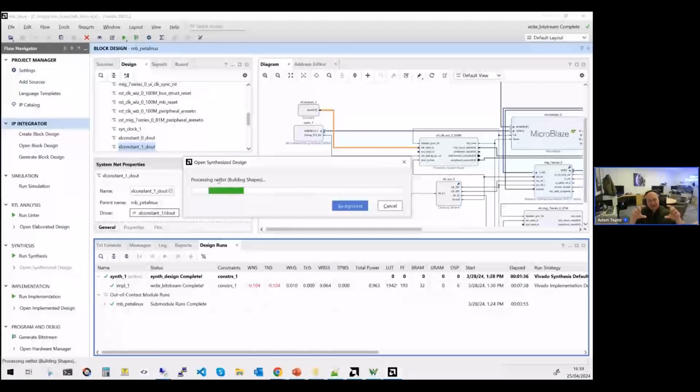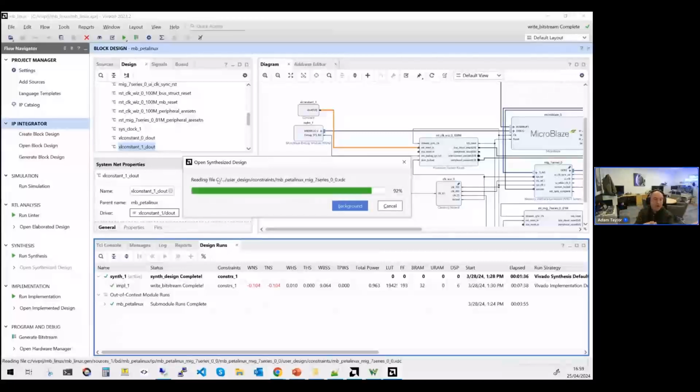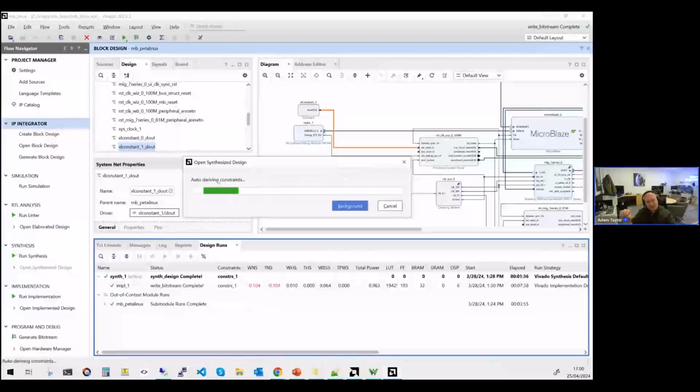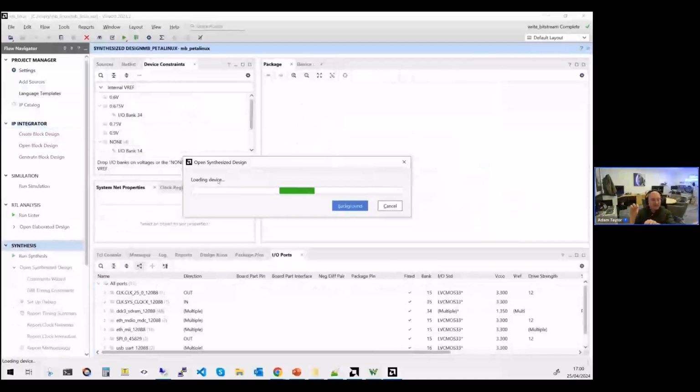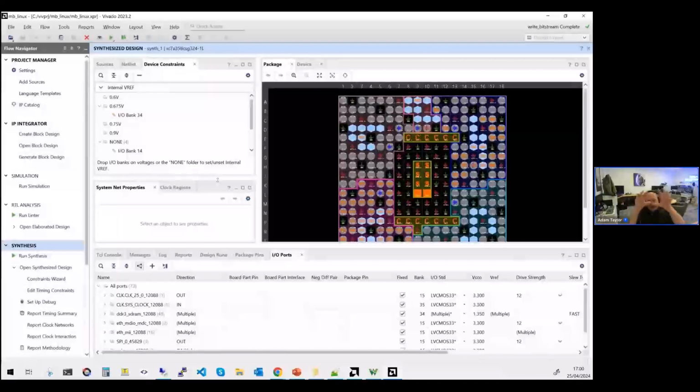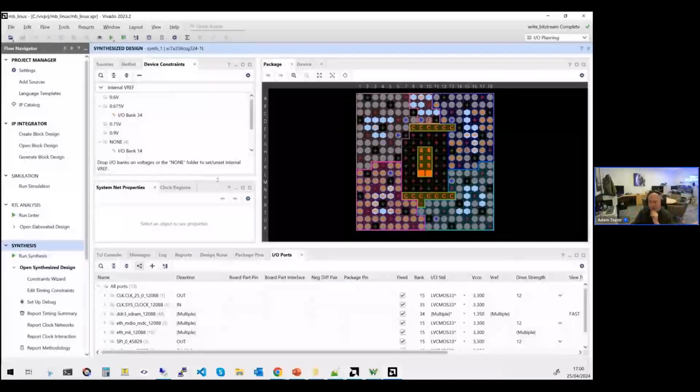And then at the end of that synthesis, it takes those modules and does the full overall synthesis, pulling in the synthesis results from the pre-synthesized modules. What that means is if we change a little module somewhere, we don't have to resynthesize everything, which might take a long time. We just have to resynthesize the module that changed and the overall top module.